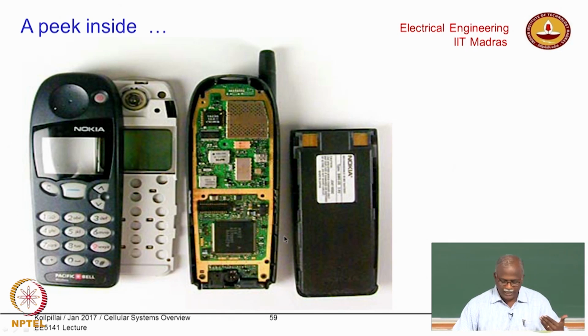Now if you remove the keypad, then the insides of the phone. Always good to start with the antenna. Antenna at one end, microphone at the other end. So basically you know which end is which. So your audio signal goes in here, gets processed by the DSP, then gets converted to the intermediate frequency, to the RF frequency, and right here you see some metal shielding. That's the power amplifier. Now why should the power amplifier be at the top?